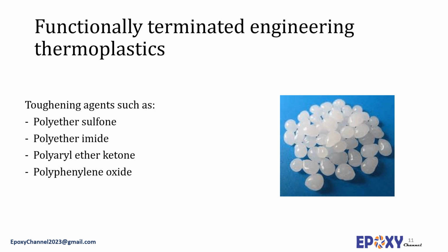These are chosen to improve toughness and not to negatively affect the high temperature performance. Due to the high modulus and Tg of the thermoplastic modifier, the modulus and Tg of the thermoplastic modified epoxy resins will reach or even exceed the corresponding values of unmodified resins. In addition to improved fracture resistance, this modification leads to reduced shrinkage in cure.